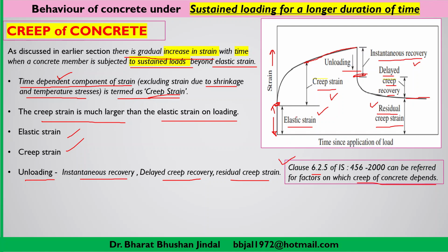Creep is basically a strain when the concrete member is subjected to sustained loading, that means loading remains sustained for a particular duration of time. So every RCC structural member will have some strain, and that strain will remain within that member. That is basically the residual creep strain which we are interested to understand.